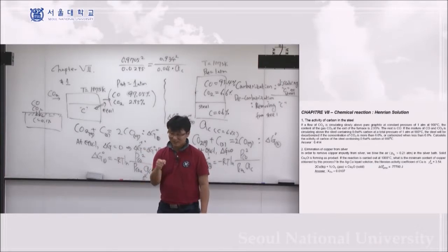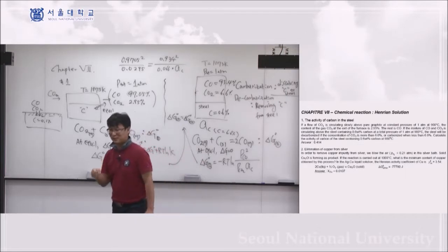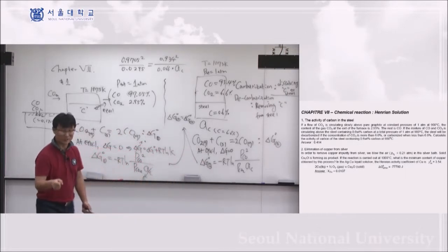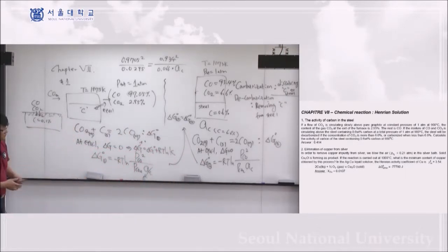There's actually the entire metallurgy of steel hidden in the sword making process. Anyway, so that's exactly this process. And in the other way, if you have very high carbon steel, and I want to intentionally remove some of the carbon on the surface, then you can do decarburization. So it means you can add a huge amount of CO2 gas, then it will start to reduce the carbon into the gas phase, producing more CO gas.